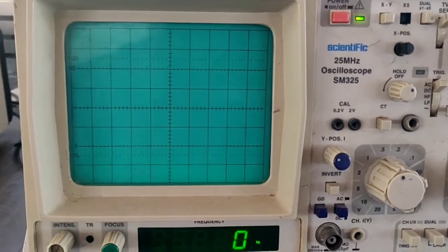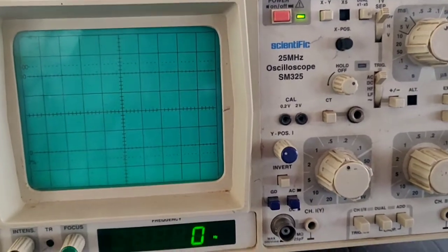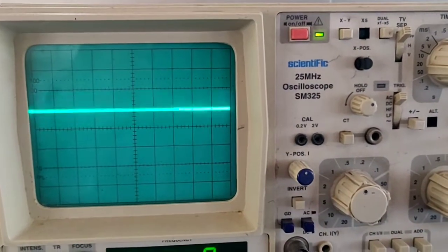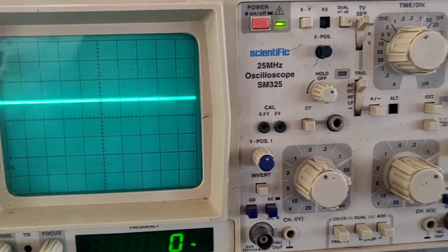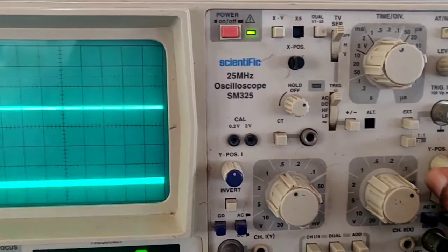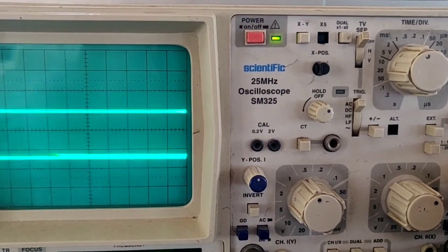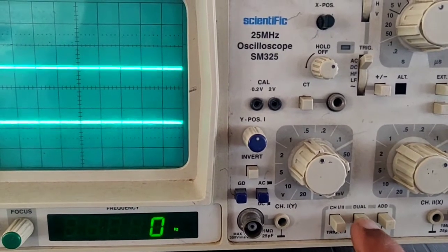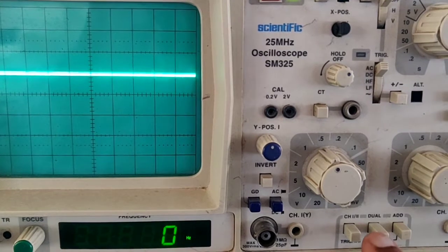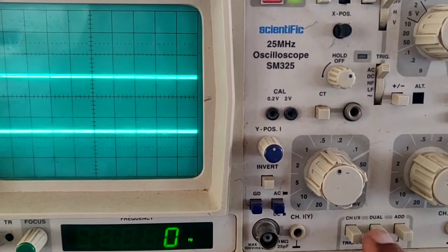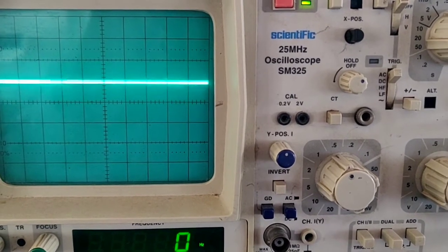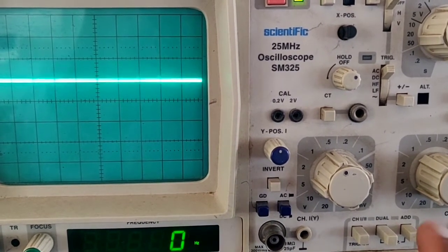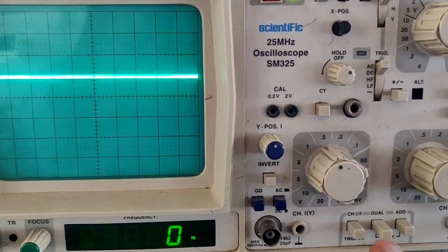Here you need not worry. The next step, you have to adjust the up and down control of the first channel here. See that, this is what you have to do. If you want 2 channels, then you have to go for the second knob and adjust this. Sometimes even if you adjust this, you will not get the channel trace, because if you select this dual channel to mono, one channel will disappear. Did you observe that? This is in dual mode, and if you release this key, it is in mono. So keep in mind that when you require only one channel initially, don't go for dual. When required, only then select it.